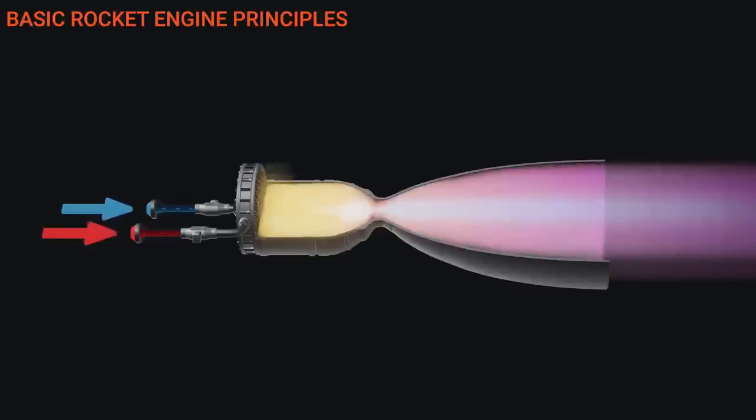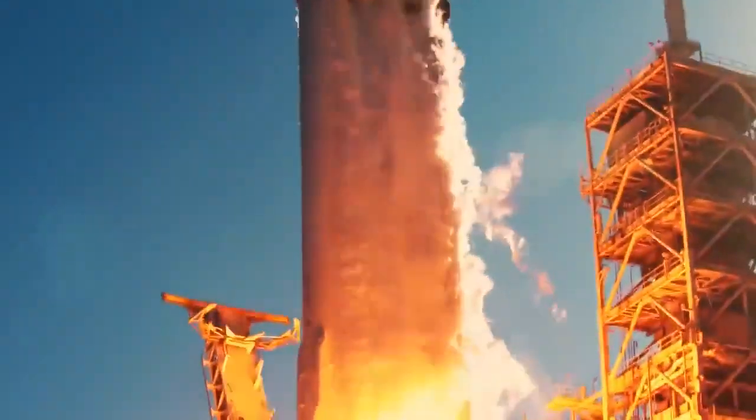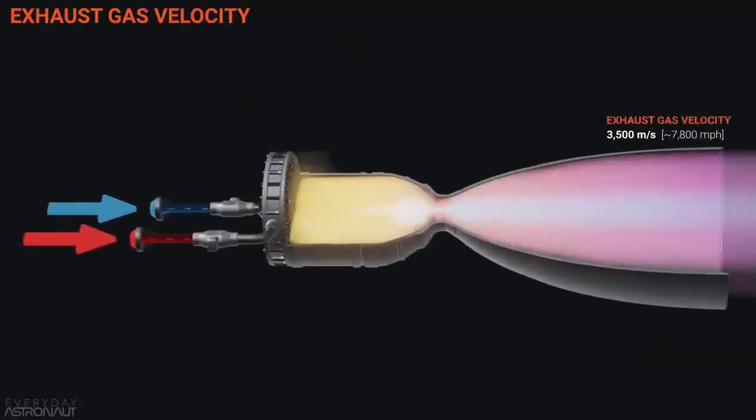Throw stuff out the back as fast as possible, period. The more stuff you can throw and the quicker you can shoot it out, the more thrust you can produce. The more thrust you can produce, the more stuff like fuel and payload you can lift, and the further you can potentially go in space. The speed of your exhaust is known as exhaust gas velocity, and it's not only directly related to the thrust that pushes back on the vehicle, but it's also directly proportional to the efficiency of the engine. So the faster we throw propellant out the back, the better.